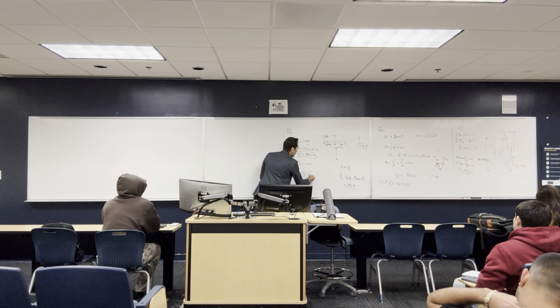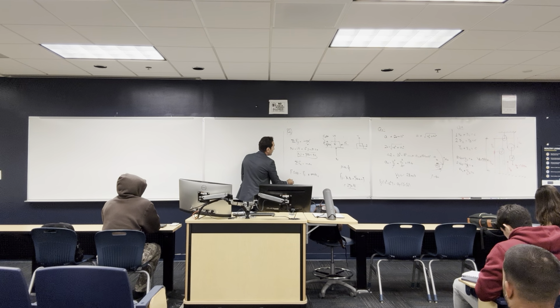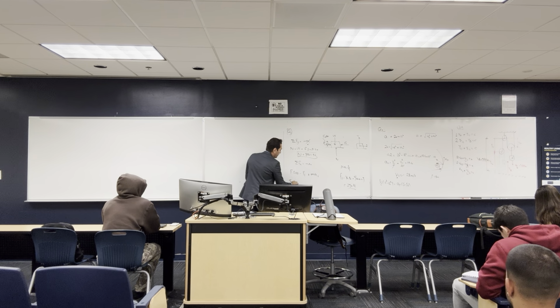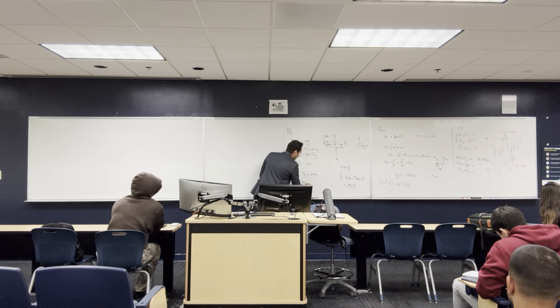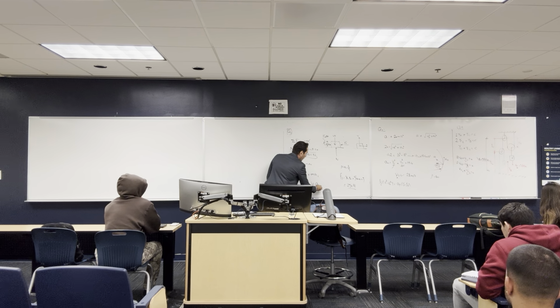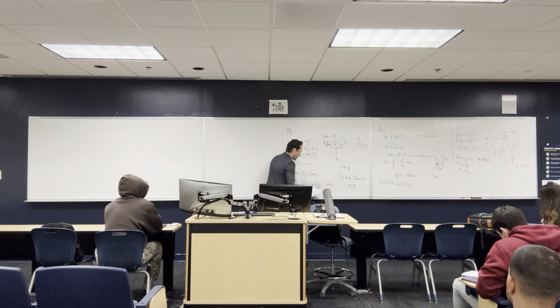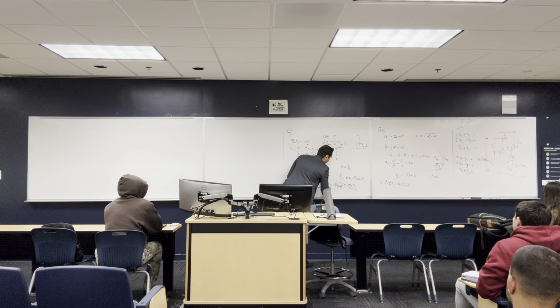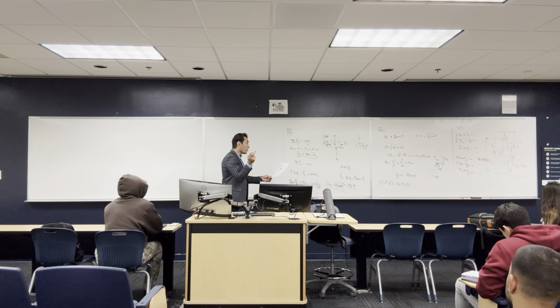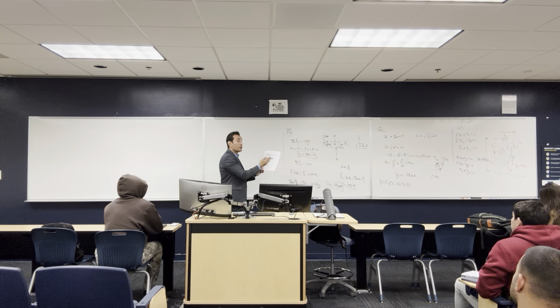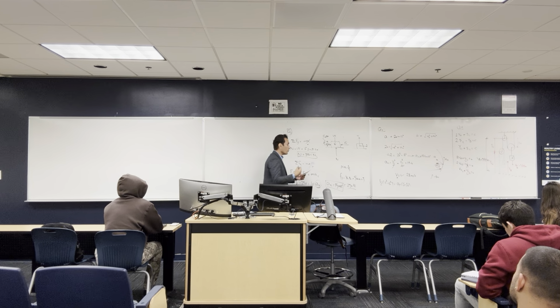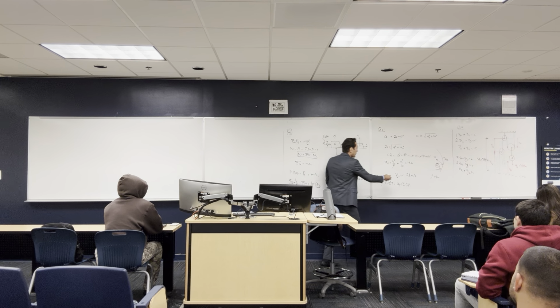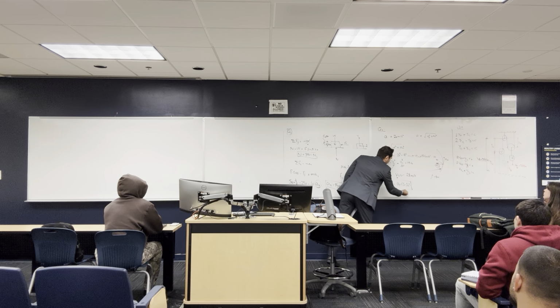So all this is going to be equal to the mass multiplied by AX. So you know already that the force is 500 Newton multiplied by cosine theta, which is 4 over 5, minus Fs in the spring, 250. The mass is 10 kilogram, given. So AX is very easy to get from the second equation. You're going to get it as 15 meter per second squared. So once you have this, you can do some Newtonian kinematics, because if you have the acceleration, and I told you it starts from rest, you can use this equation to find the rest of the problem.